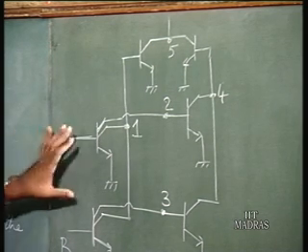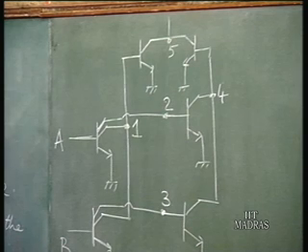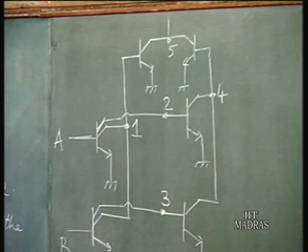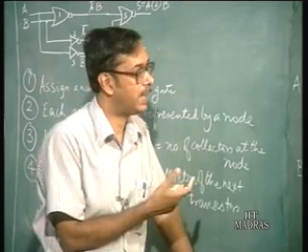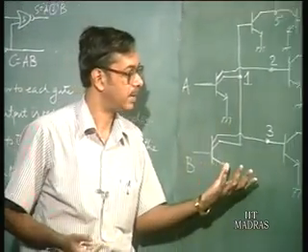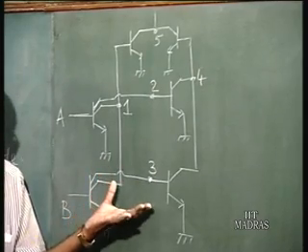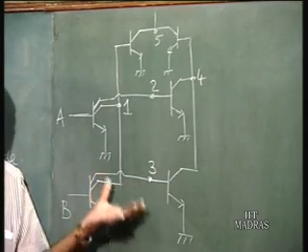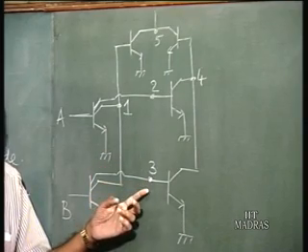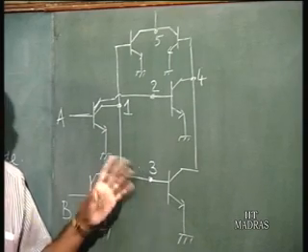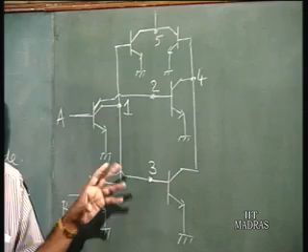That particular circuit can be represented by this layout. Of course, one thing is that we have not drawn the PNPs, we have just drawn the NPNs. In many cases you will find in textbooks that the PNPs are not drawn, because it is always assumed that at each base you have a PNP. So, you need not draw it.